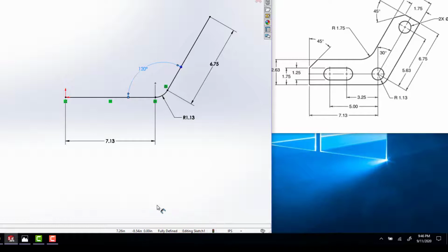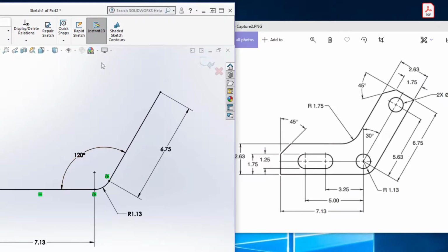All right, so what I'm going to do now is start from here. I want this to be perpendicular, and then I'm going to go off at a 45-degree angle and then come down again. So I'm just going to do those quick 2 lines here. I'm going to make my line. I'm expecting that when I click here and start drawing my line, I should be able to see the parallel and the perpendicular. So that's the perpendicular that I want. Now notice that white vertical constraint is telling me that if I click here, I'm going to be directly above the center point of that line. I don't want that, but it's not going to put it on anyway.